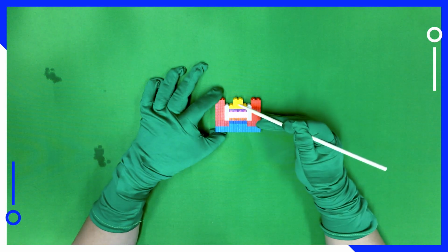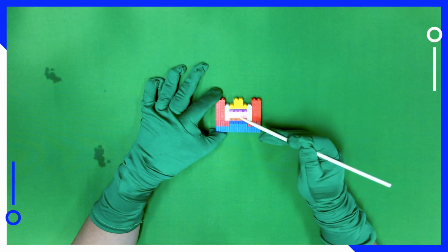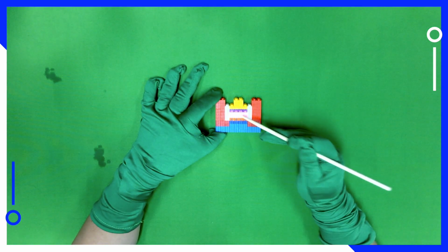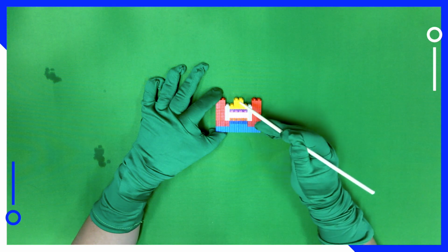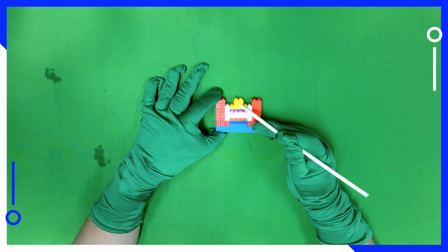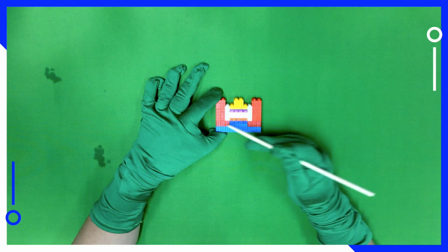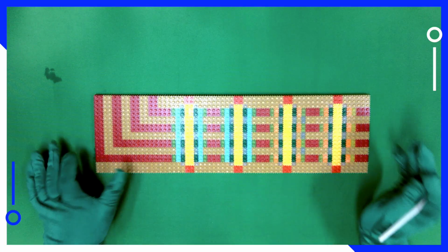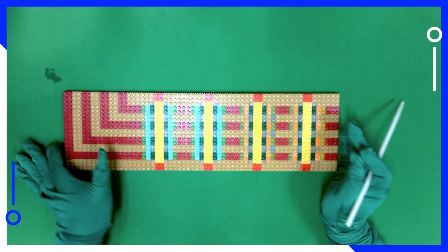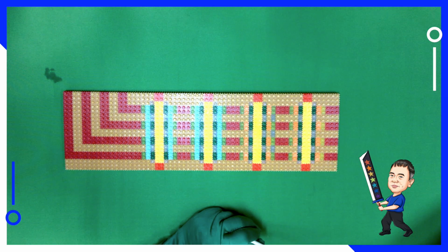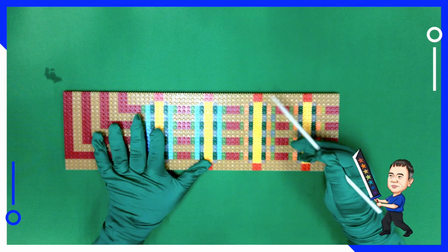If I apply a certain voltage, then only when the floating gate has charge will the current go through. If I apply a voltage on the control gate high enough, the current will always go through. That's the way to get the information out. So why do I need to apply a voltage high enough? So here is what I do.